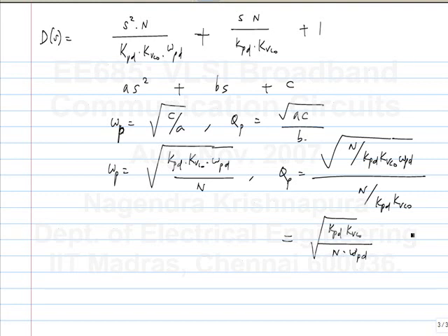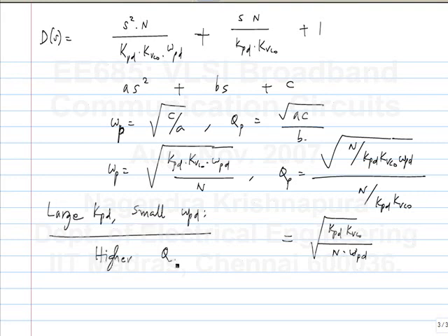Okay. So, what does this say about making it a low pass filter? The idea here was we will make K_PD large and omega_PD low, so that the gain at high frequencies is small, right? That was what we were doing. Okay. So, as we go on doing that, we get higher and higher values of the quality factor. So we can't do this because, yeah, that's true. This will give a large value of K_PD at DC, but it renders the system almost unstable.